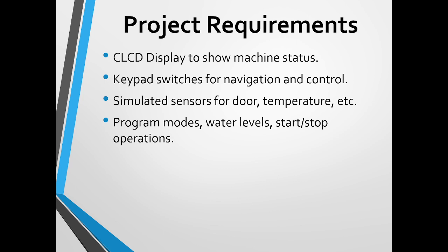So the project requirements are a power on screen that reacts to button input, then the selection of washing modes and water levels, then real-time status display on an LCD, motor control through relays, and proper handling of door status using sensors and buzzer.